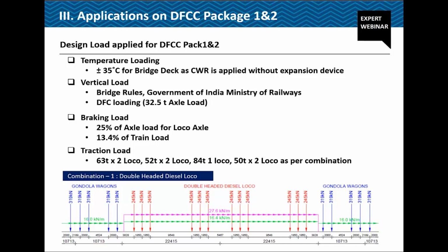This diagram shows the configuration of this train combination. This is combination 1. In this case, we have a 31. This part is a wagon, and this is a loco. Usually, loco has a much higher acceleration force, whereas this wagon has no acceleration. And in terms of braking, as you can see, this green line, this loco has somewhat higher intensity than this gondola part.